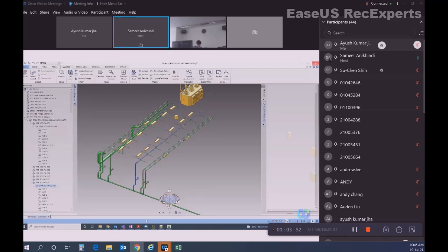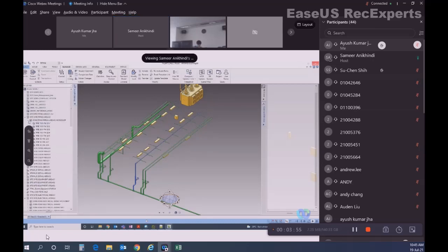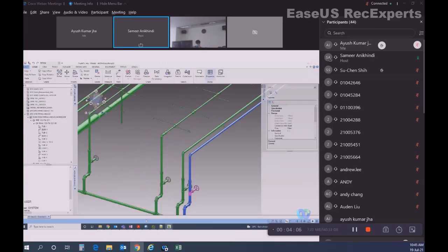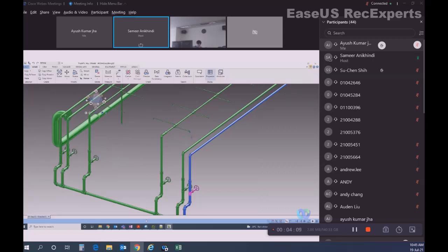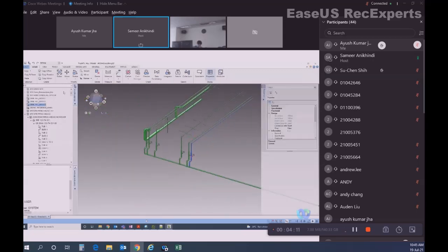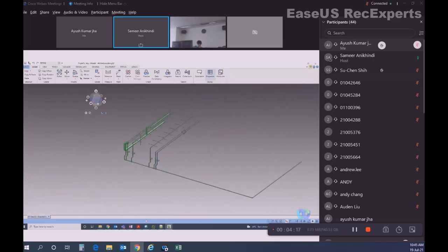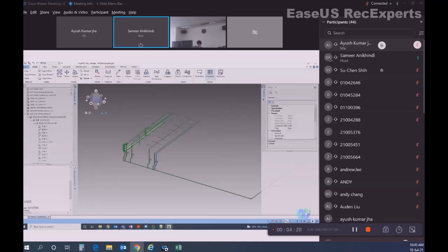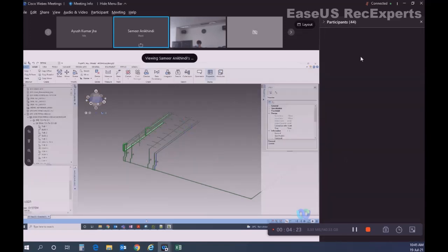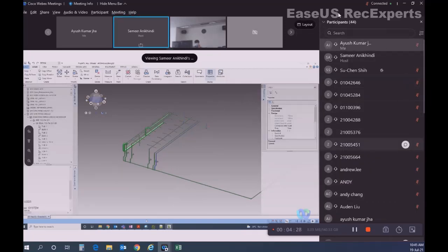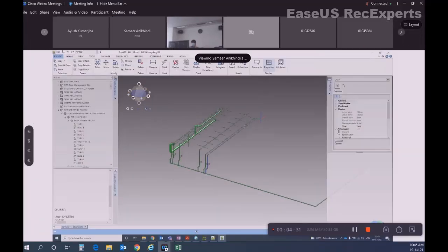So this is how you save work and get work. There's a little shortcut key which I need to tell you. If you press F2, it will clear the canvas. It will hide the properties window and model explorer, and it will give you more space to work around. If you press F2 again, it will bring these back. So it's like a curtain, curtain on, curtain off. Okay, F2 is the key.